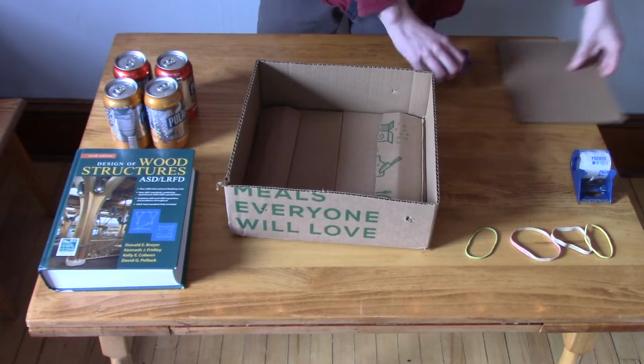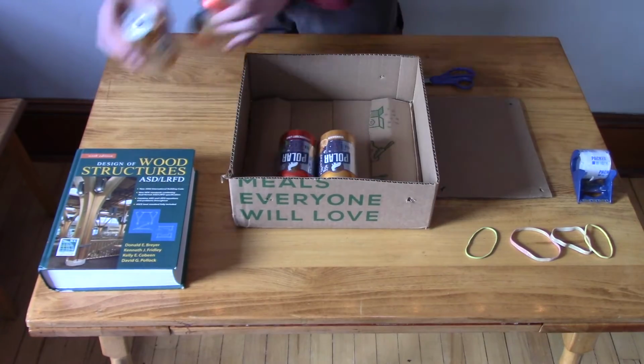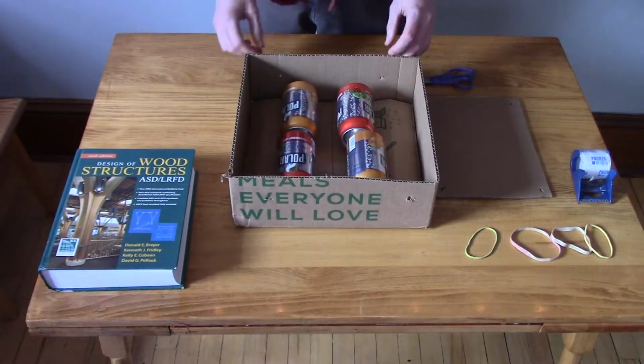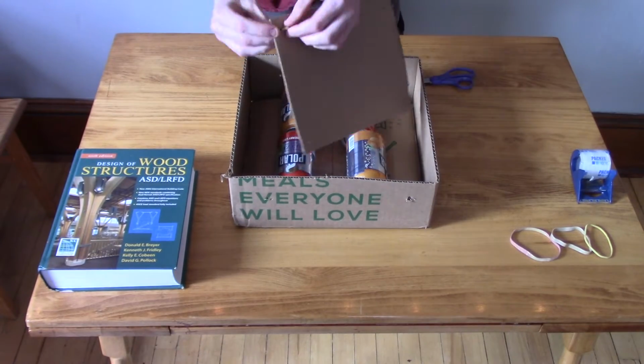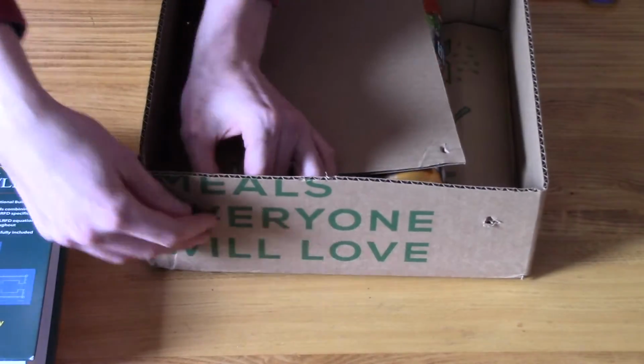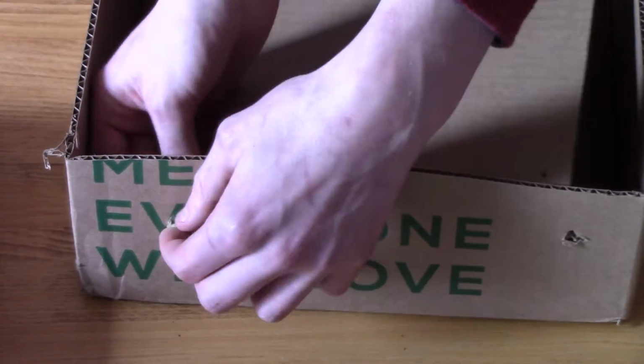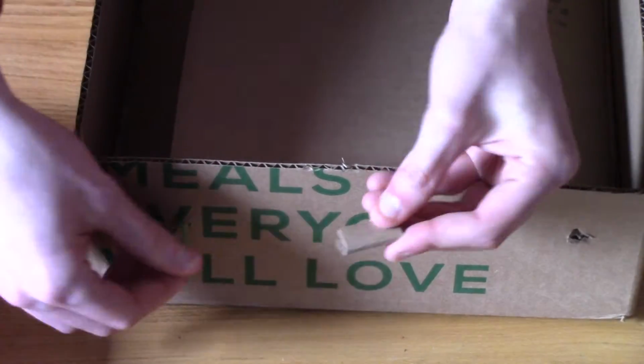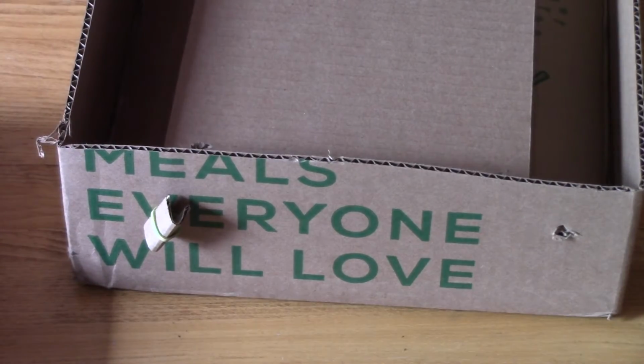Here we're placing the rollers inside of our box and the modeled ground surface on top of them, as well as 2 cardboard spacers to prevent the rollers from sliding out from under the ground surface. Next, we will secure the ground surface to the box with rubber bands and small pieces of cardboard to ensure the bands are taut. Structural engineers use shake tables to model the effects of earthquakes on structures.